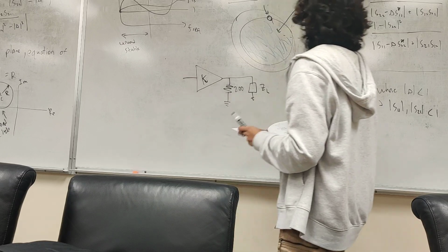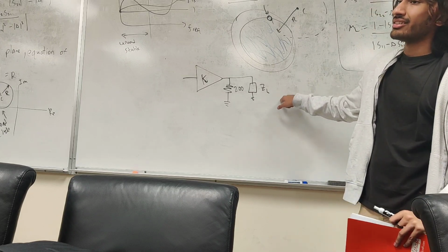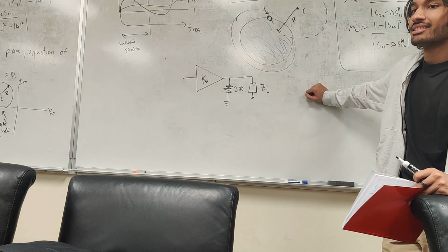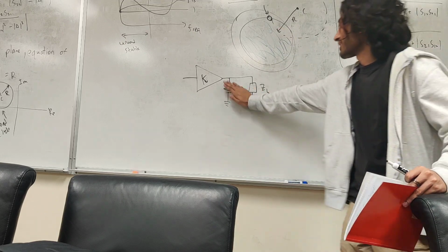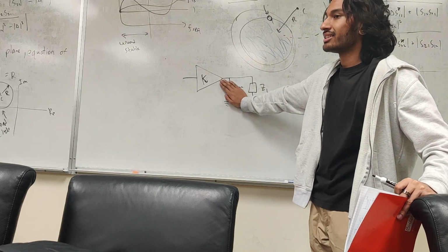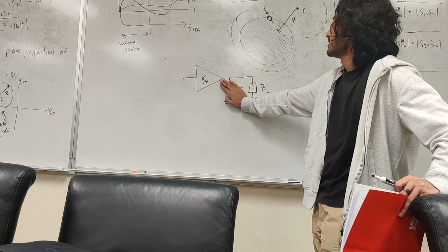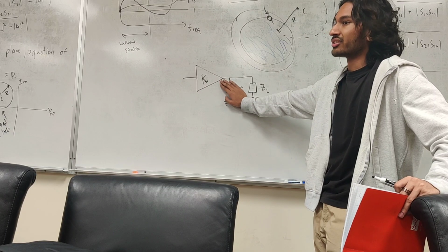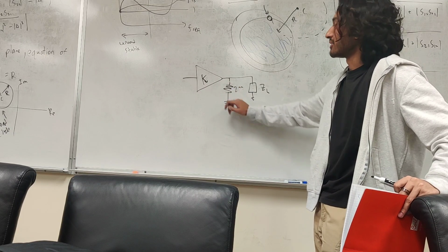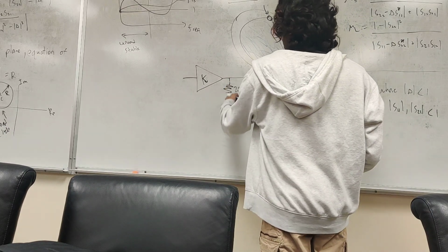We do this. This way, 200 ohms in parallel with anything is always less than 200 ohms, right? Which means no matter what, we're going to be here. So before, it was just like this. You had the ZL, and 200 ohms was the value at which, for ZL, that's the boundary point. We put 200 ohms at ZL, no matter what ZL is, we're now less than 200, right? So that's a neat little trick. We can put something in parallel.